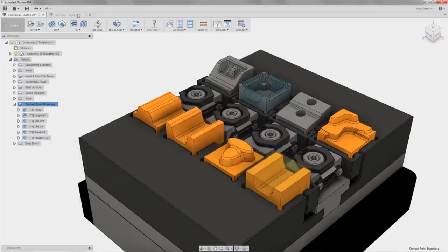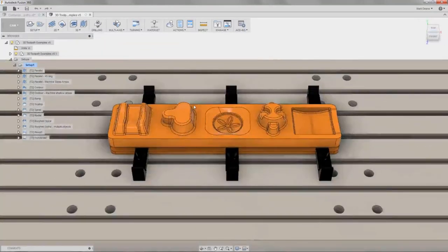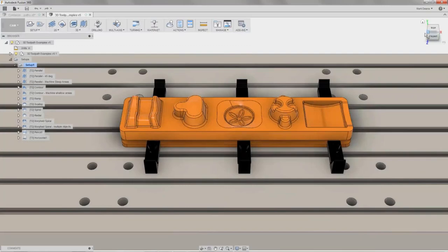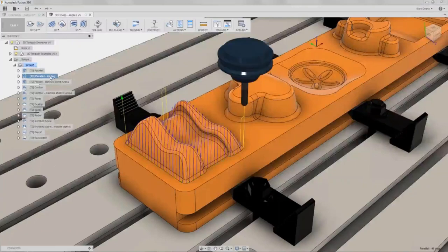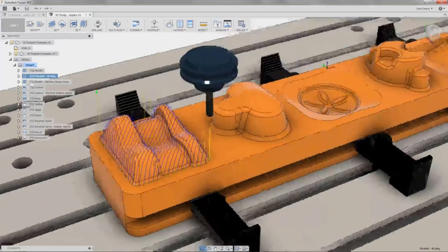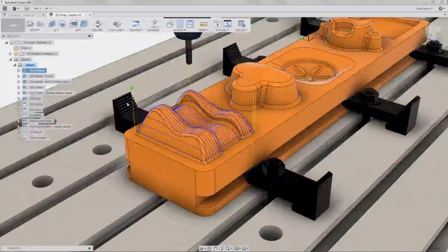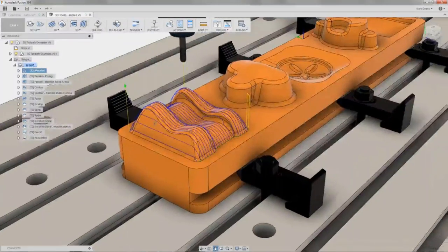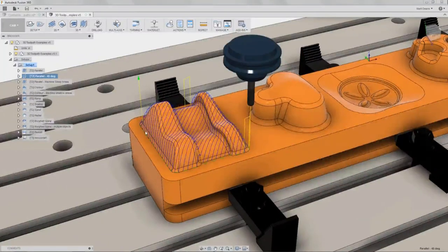So that's post-processing, and we have under 10 minutes left, 7 minutes. On this part, I was just going to go through and talk about individual operations in a little more detail, but we went through parallel already. My one best practice tip with parallel is going at 45 degrees can often fix a lot of problems. In this parallel, going straight on or in one direction, obviously these draft faces get compromised pretty badly. But going at 45, because you're just bisecting the problem area, it sort of becomes not a problem area.